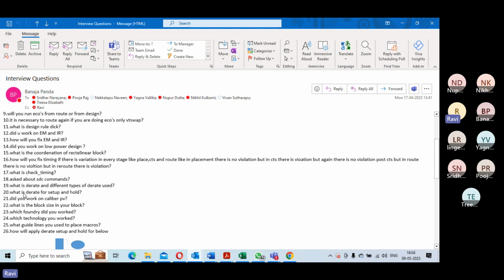And on top of that, you are applying derate. With derate, it's quite possible that your worst arrival path for setup may not be your worst delay when derate is applied, because its impact will be slightly different. So there is the launch clock derate, the data path derate, and again, in the data path, the cell derate and net derate.